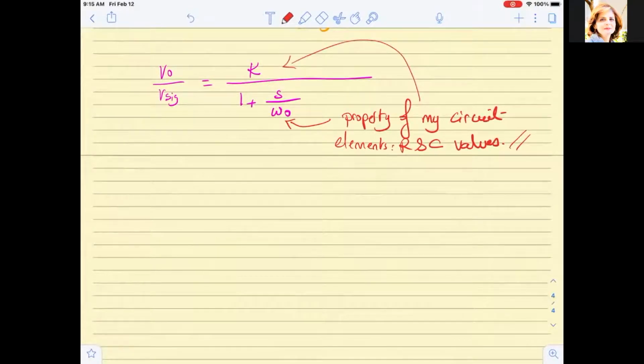So if we want to look at a set of given values for this circuit, in the slides we are given Rs equal 20K, R sig equals 20K, Ri is 100K, Ci is 60 pico, AVO is 144 volts per volt, RO is equal to 200 ohms, and RL equal 1K.